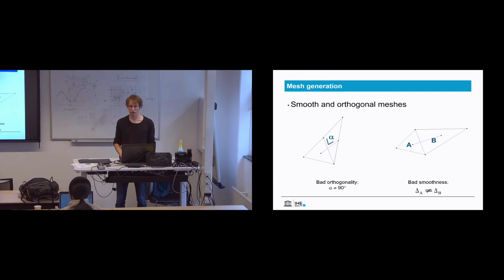It's important in Delft3D 4, it's even more important in Delft3D FM. So whenever you work with triangles, probably your orthogonality needs to be an order of magnitude better than in Delft3D 4. So I think the general guideline in Delft3D 4 is 0.1 or so. Well, for triangles you need 0.01 to 0.03.